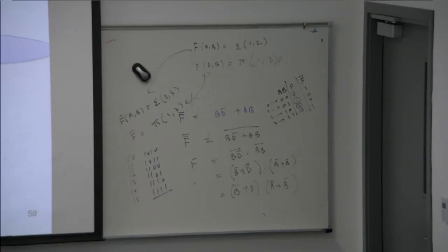So now we have an unreduced SOP expression with 11 literals, and we have reduced it to a reduced SOP expression with how many? 6 literals. So this is an example. I may also give you a SOP expression which is reduced compared to the standard sum of the minterm form, and then you need to further reduce it. This example 2 is that example. Got it? So please go through all these examples. If you are practicing at home, this is your question: I want to further reduce it, and this is your answer. Got it?